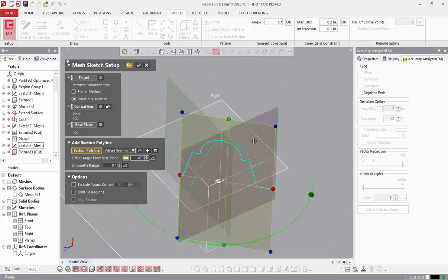And just like in what I'll call 2D mode or the planar method, I also have a silhouette range. This is a little bit harder to give an analogy to because we can't really bend light. I'm not a physicist. I think maybe it's possible, but basically this works the same way. If I'm missing data in certain areas here, I can grab this fat arrow and now I'm creating a wedge, right? Instead of just a 2D cross section, I can take a 3D cross section, and all of the data within this wedge is being compressed down and averaged and projected onto that plane.